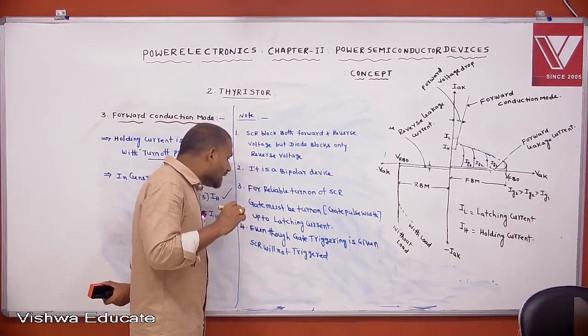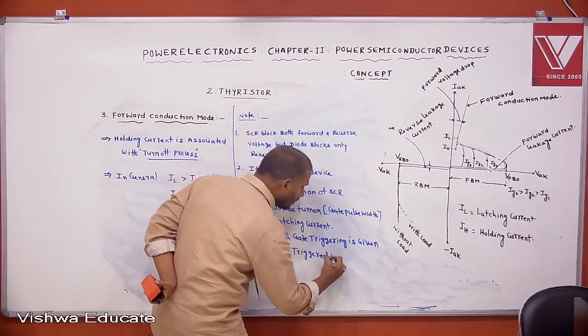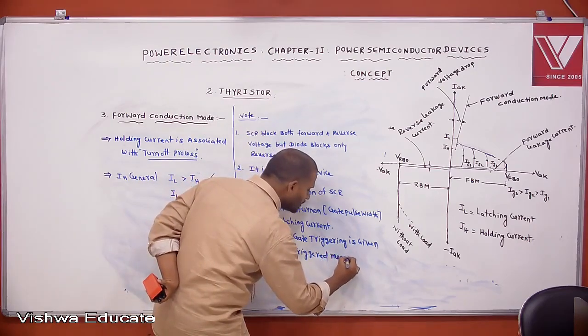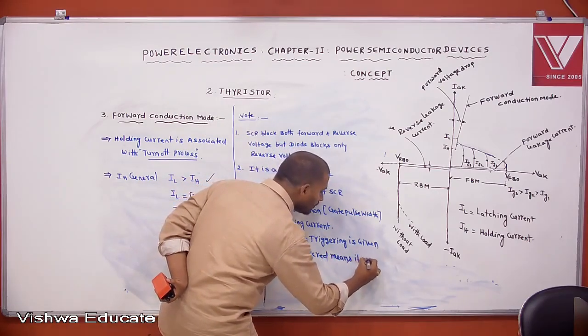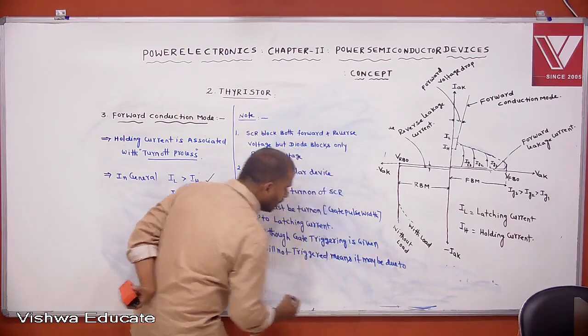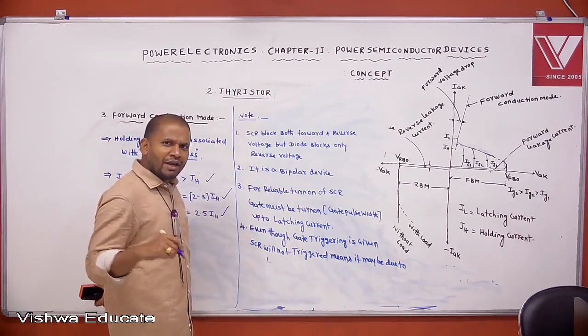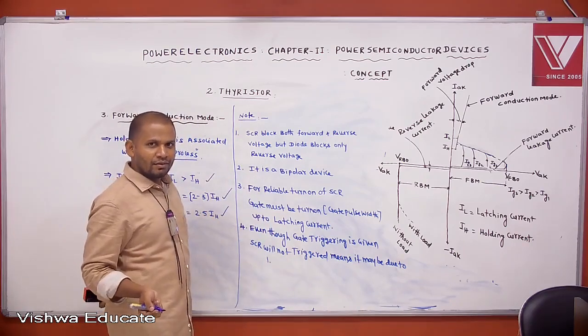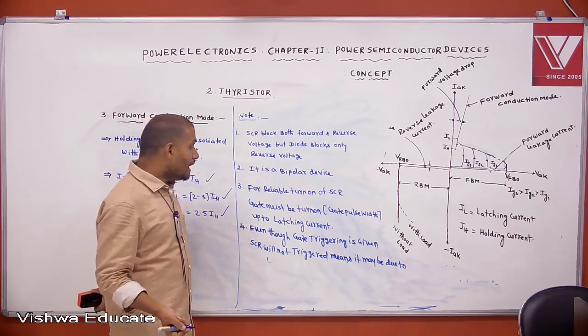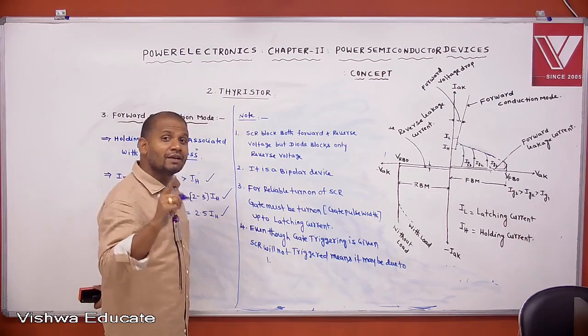You are giving gate supply, but it is not triggered. It may be due to the SCR being under reverse blocking mode.